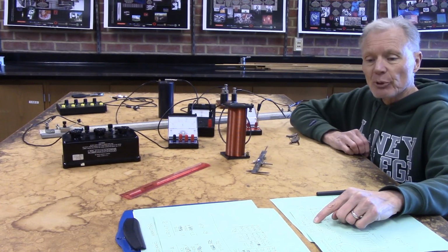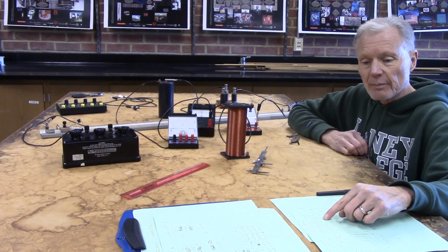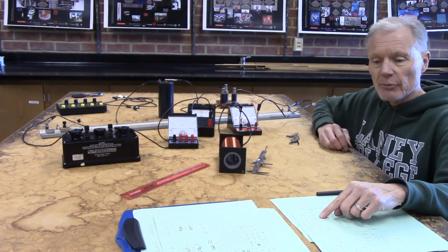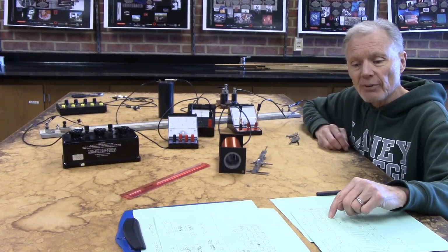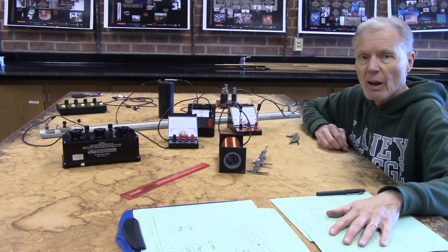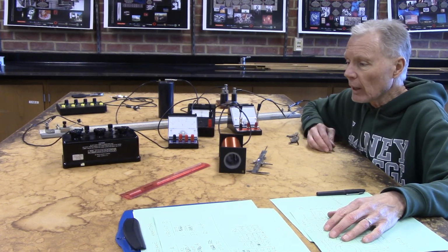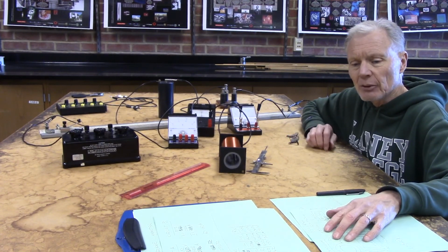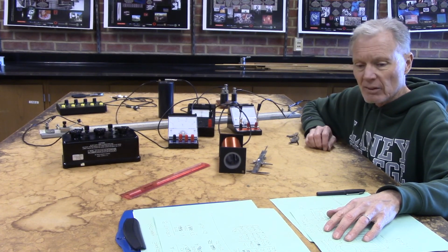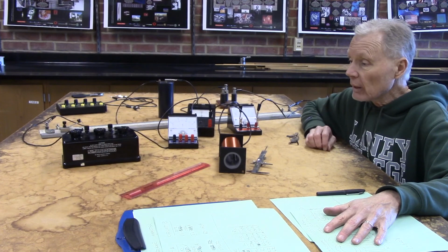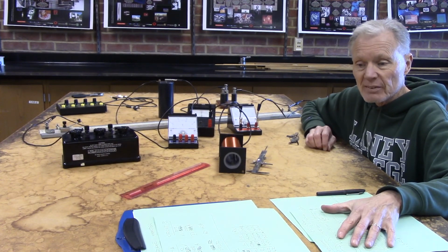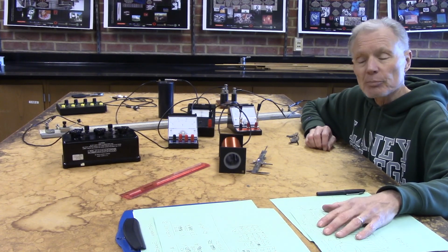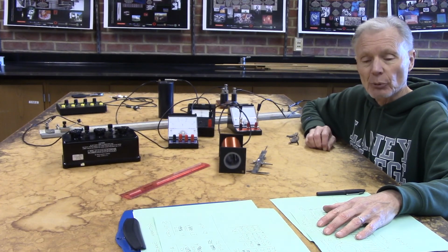That gives me an average circumference of 17 centimeters, and multiplying by the 560 loops gives 9,500 centimeters or 95 meters. I think before I was suggesting that there might be like a kilometer of wire on this, and I think I exaggerated. It looks more like it's a little under 100 meters of wiring that's on here. So with that, we can take the resistance measurements that we came up with, include these dimensions now, and work back and get a value for the resistivity for copper.